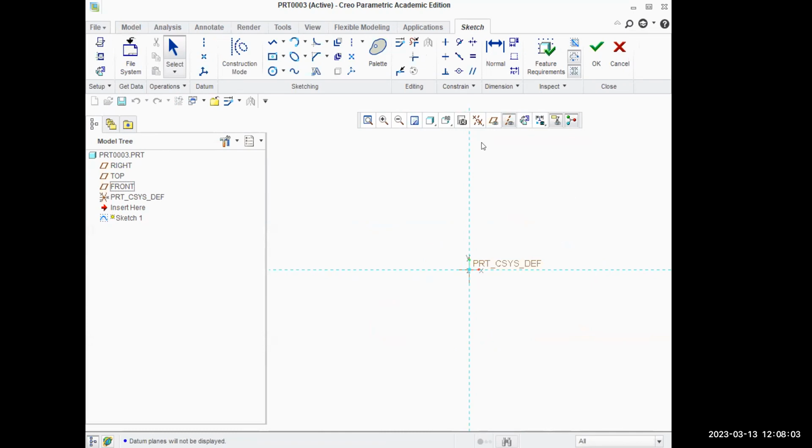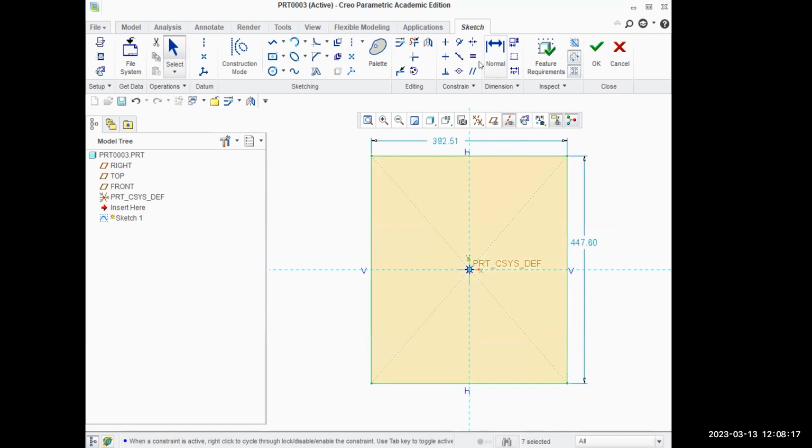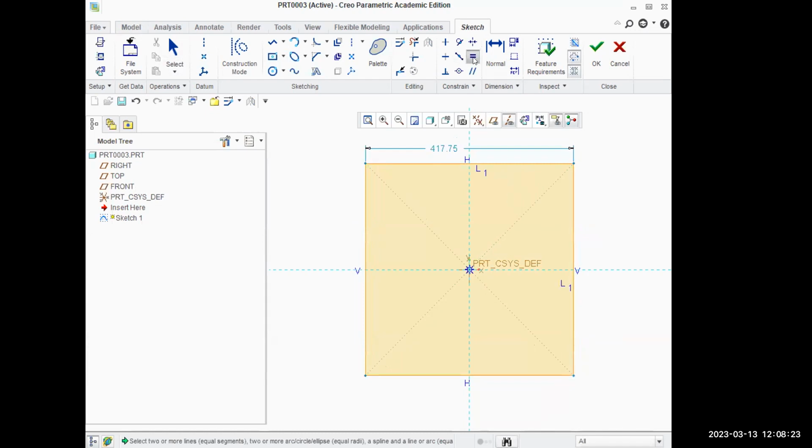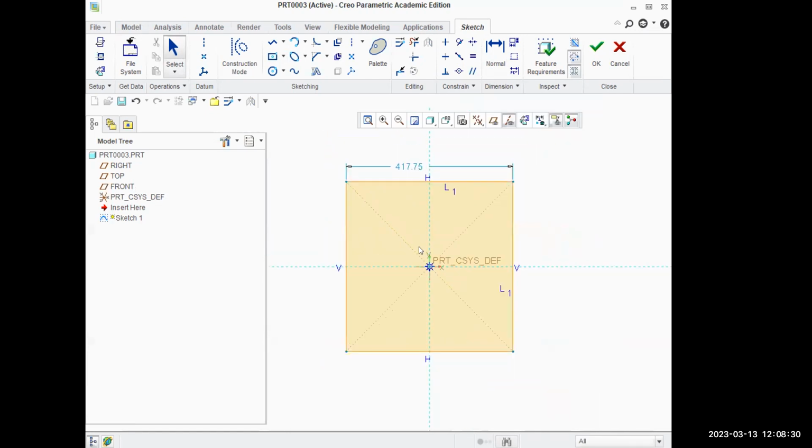So here, first we should draw a rectangle of 80 by 80. I mean a square of 80 by 80. As this is convenient, I am going to take the center rectangle and draw. As this is a simple geometry, simple profile, I'll make these two edges the same length by making use of the equal command. Come out of the command, press the middle button, drag.